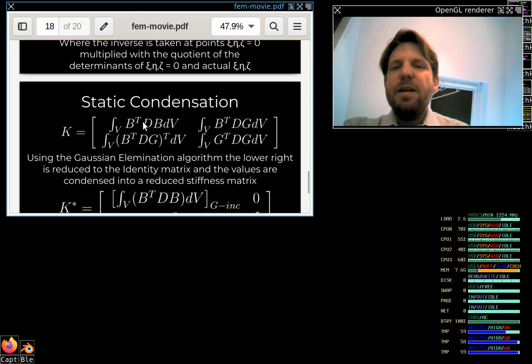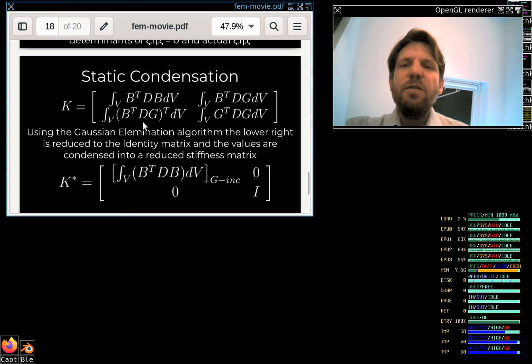And then people do something that is called static condensation. So with static condensation, of course, you don't want to blow up your system, so you don't want, first of all, to have a bigger matrix to perform the final calculation, because it's already hard to do this. I mean, hard to do. You have numerical algorithms that we've implemented in order to solve these linear systems rather quickly, but K gets very easily quite large, and then you add these coordinates, so you don't want to do this.